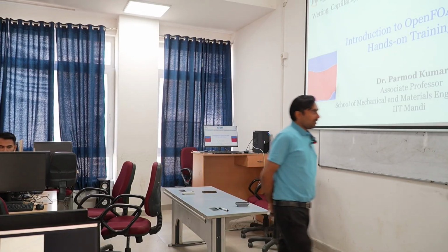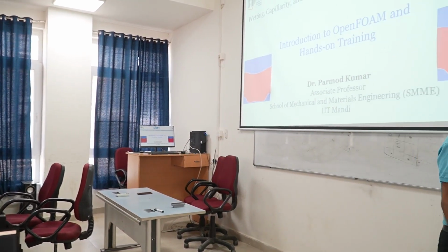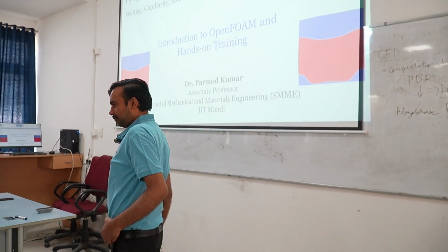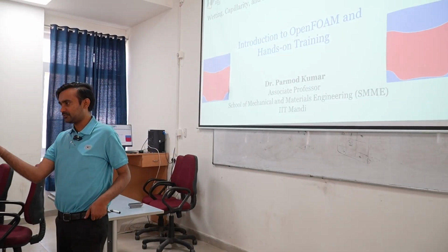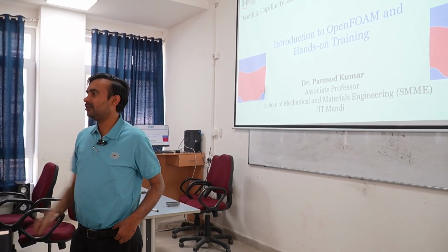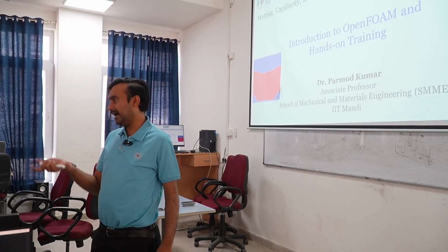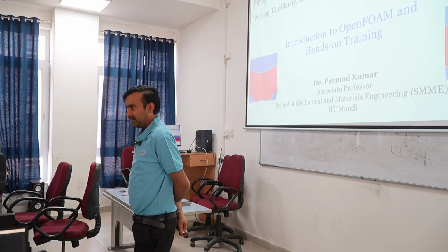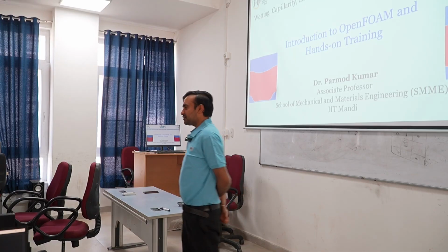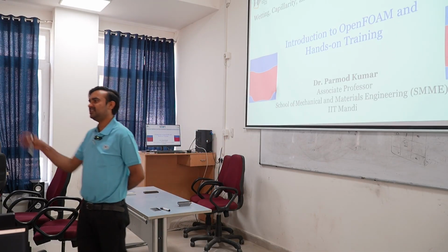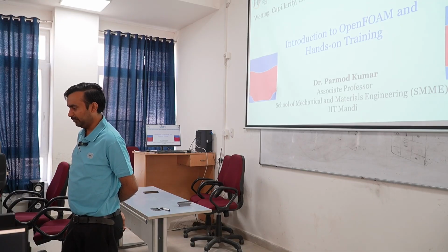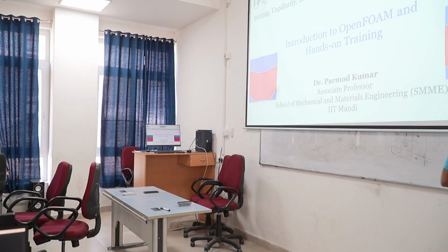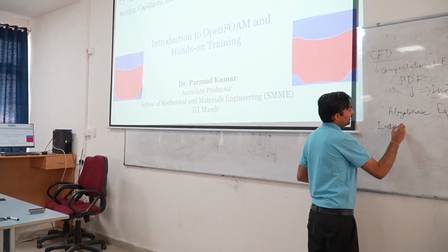What we will do here: OpenFOAM, as I told you, is available for a wide range of problems. For example, if you have to do a conjugate heat transfer problem, then there will be some other solver available in OpenFOAM to do that. If you have to do some multi-phase flow problem, then there will be some other solver available. If you have to do some single phase flow simulation, for example flow through a pipe, then there can be some other solver available in OpenFOAM. Among all these solvers, we will try today to use the one which is called InterFOAM.